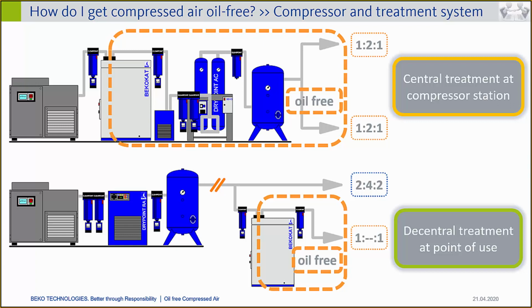Pressure drop may increase because particles will enter the system, and when particles enter the system and are collected in the catalyst tower, they will reduce the open space for the airflow, and that will result in a higher pressure drop. So from that point of view, it would be recommended to place an additional filter upstream to reduce the risk of increasing pressure drop.